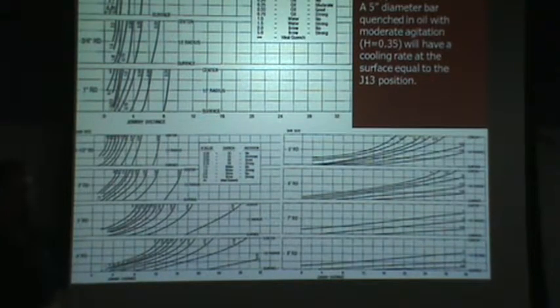In each quench tank, we have 8 shafts, 8 big motors, and a big impeller that's probably 14 or 16-inch diameter inside of a big tube that's got sort of a J shape to it. And so what happens is I can turn those propellers on and force the water or polymer to circulate in the tank from the front to the back. The tanks are long and narrow, and these are all arranged along the back wall of the tank. So I can make the water kind of circle this way, right?